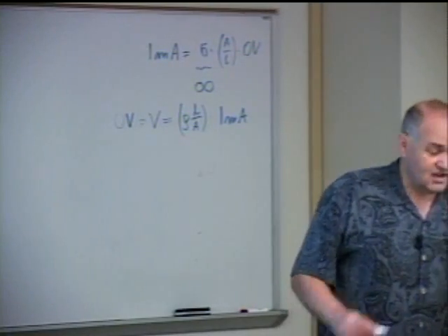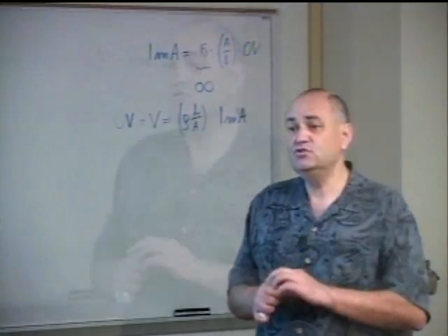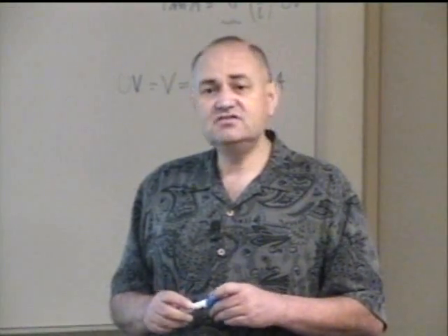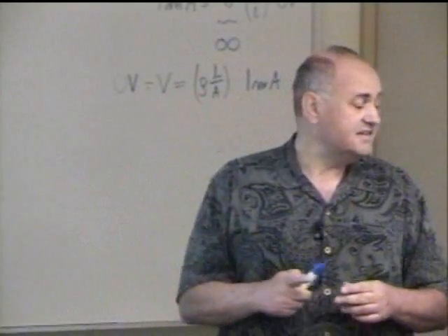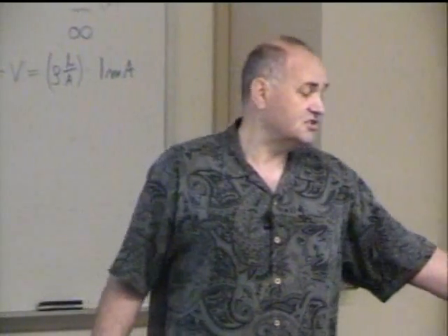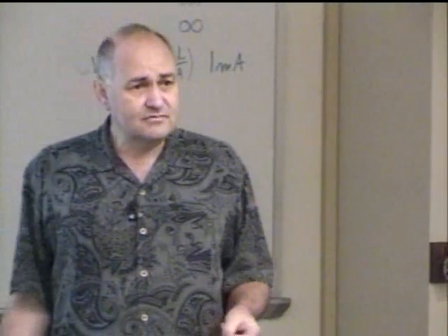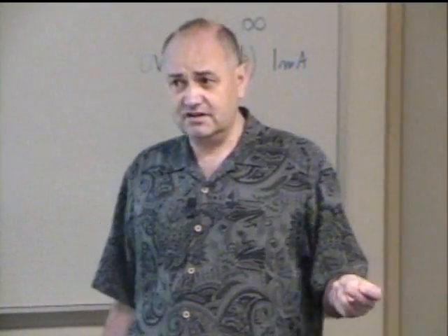And indeed, this is how we make wires. We choose substances like copper and aluminum, because they have a very high conductivity and at the same time very low resistivity. Now, if I want to make a 1 kilo ohm resistor, which is a reasonable value for a resistor used in electronics, I wouldn't take copper. Why?